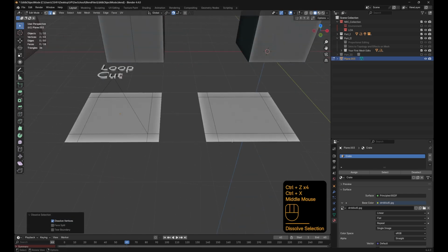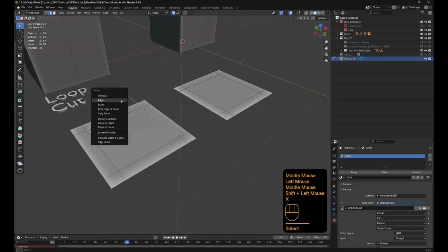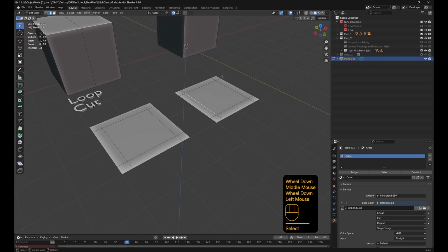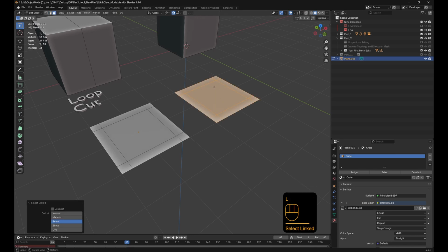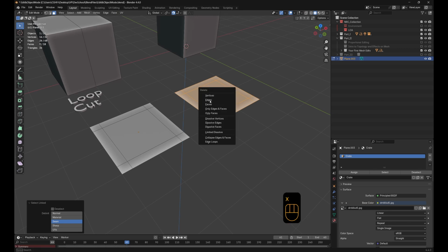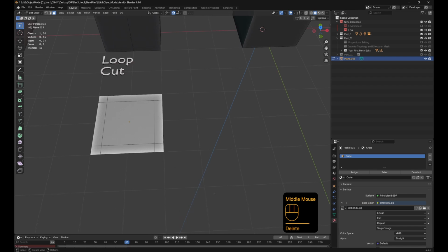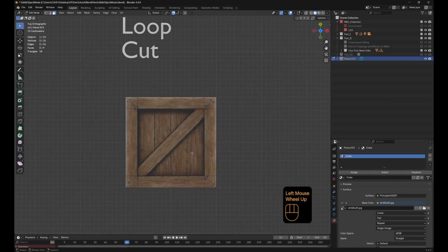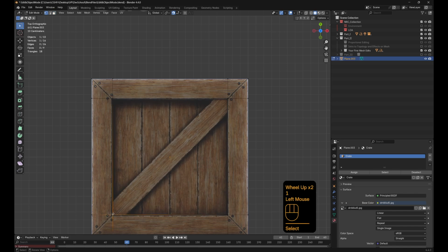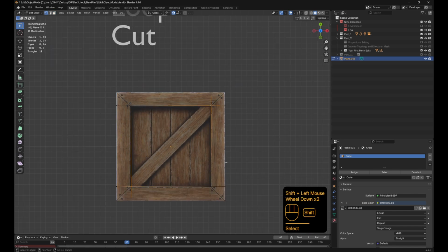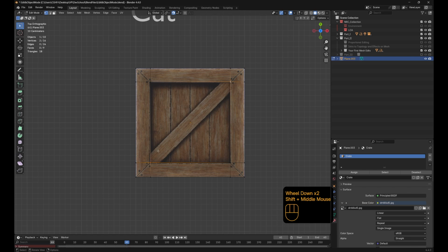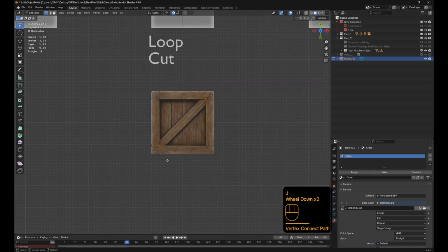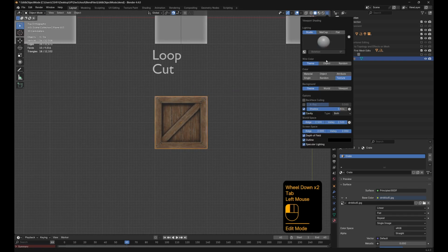I'm going to dissolve those edges and I'm going to delete those edges. I'm also going to hold my mouse over here in face select mode and press L, and that just grabs everything to do with that bit of mesh. Hit X and I'm going to delete everything. Bye bye. So using that, we've just learned about the join tool. What we're going to do is get this vertex and this vertex, and join in between with J. And that's a good starting point, I think.